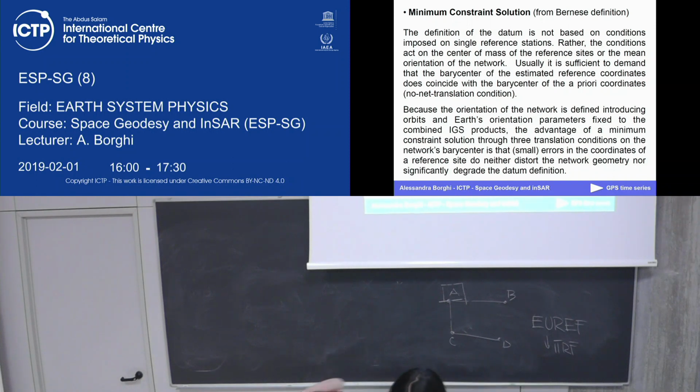You fix the orbit, so you know that the orbits of the satellites are in a well-defined reference frame, because we have seen that in the file you find the note about the name of the reference frame. Do you remember? Yes, in the SP3 file, at the beginning, in the first row, you find this information.